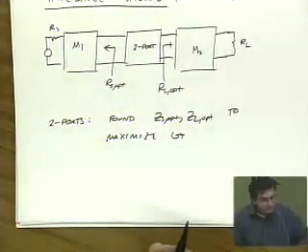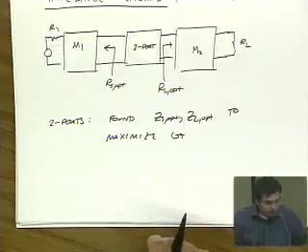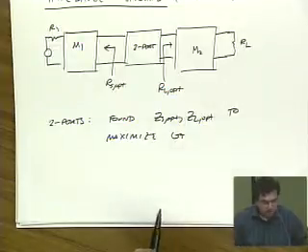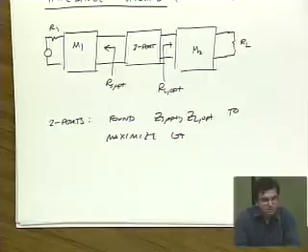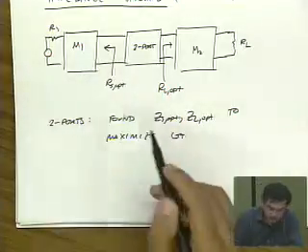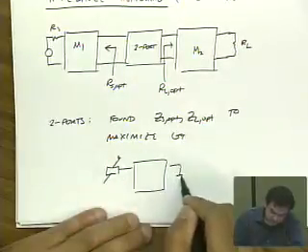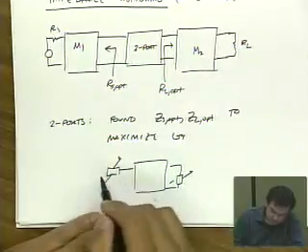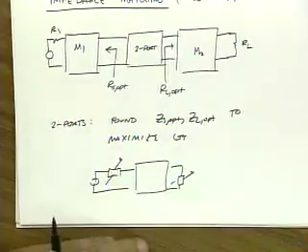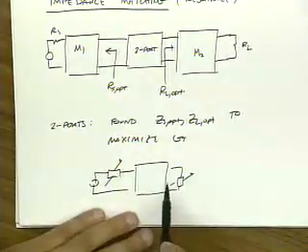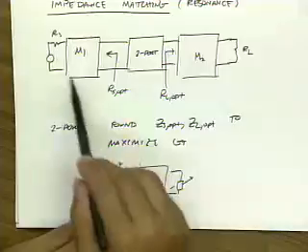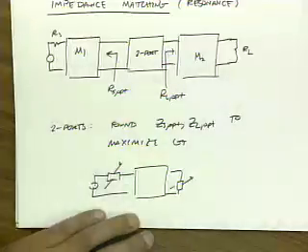How about other cases? Why else would you want to provide an impedance match? Can someone think of other situations where an impedance match may be useful? So in essence, this is kind of the knob that we were talking about. This is the ability to tune the source and load to get the maximum gain. In practice, this is how we do it. We can't really change the source and load, but we can design matching networks around our device.